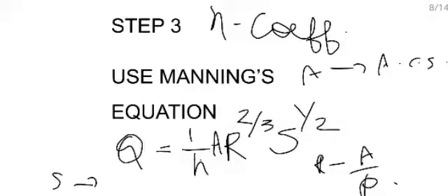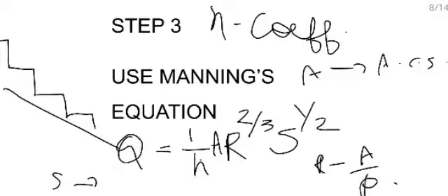If the slope is too high, as you might have seen in many areas, there is a risk of erosion. A step-by-step drain is a type of drain which can be adopted. Now, the surface can be perforated. If it is not a combined sewer, perforated drains are preferable.